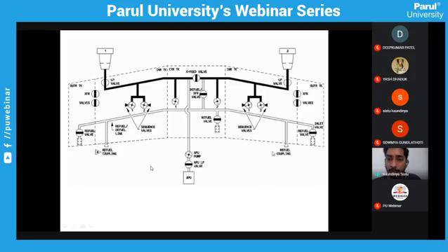Just follow my mouse. The fuel is fueled into this, and if this refuel valve is open, it will go into the fuel tank system. This will always be closed unless it is pressurized. Even if it's open, if you don't have pressure, it's not of much use. It goes to the right wing and comes here. If you close this valve, the fuel will only be fueled into the left wing.